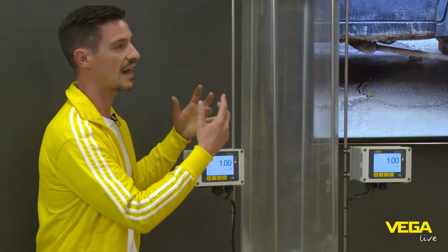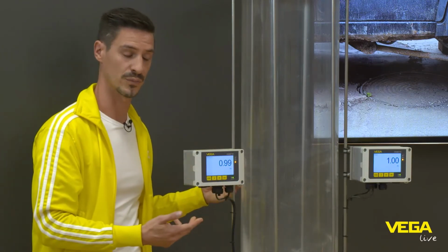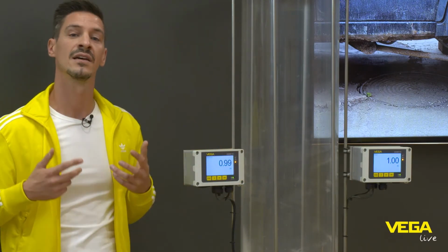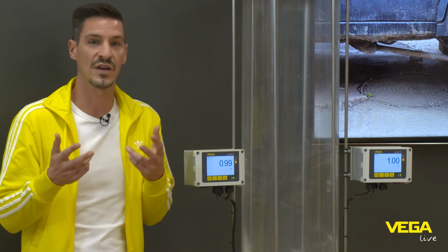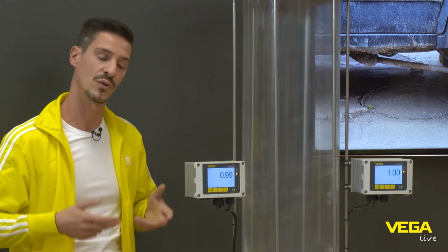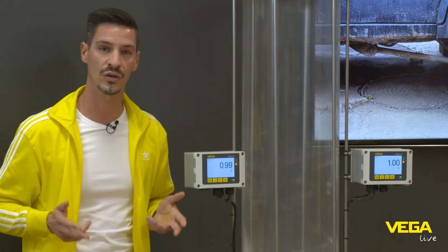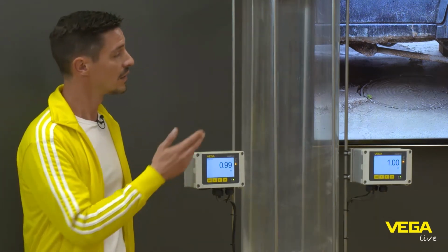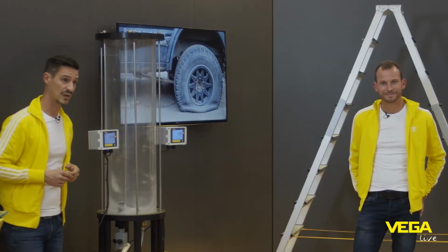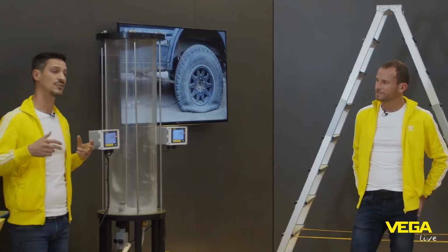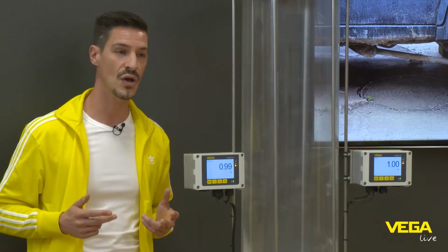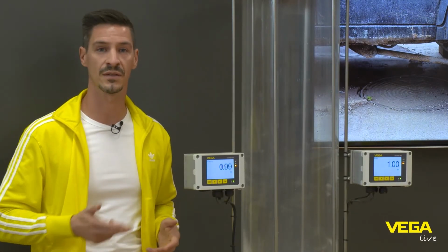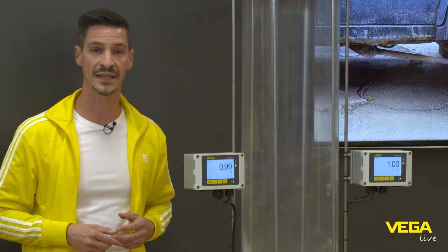Then you generate underpressure down to vacuum. And then we are taking out air, which means the ultrasonic wave has no transport medium anymore. So ultrasonic won't work under a vacuum atmosphere or under a pressure atmosphere. Compared to that, with our radar device, the electromagnetic wave has no problems and needs no transport medium. Therefore, also here, a big advantage for the radar measurement.